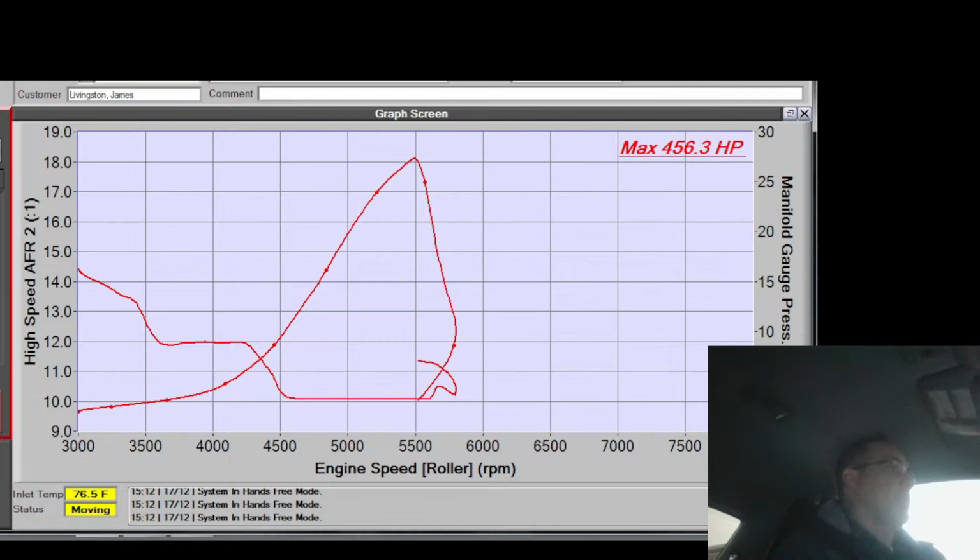Yeah, I can't stand Turbo Smart wastegates. I think the diaphragm material is poor. The spring material is terrible. The springs fail, or they just get soft. They change their pressure all the time. You know, like on really cheap, crappy suspensions, when someone puts springs on their car, like, oh, the spring's got to settle. The spring should not settle. That is not how springs are supposed to work. Springs are not supposed to change their rate and their shape with use.